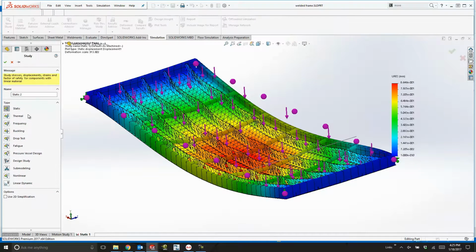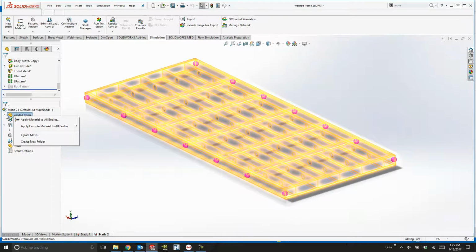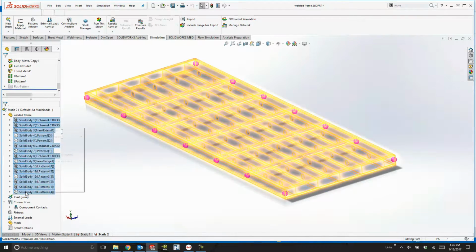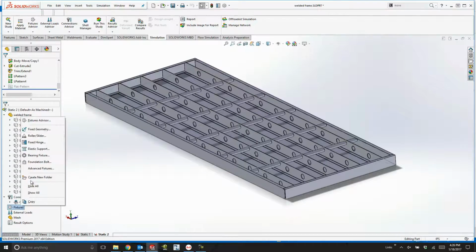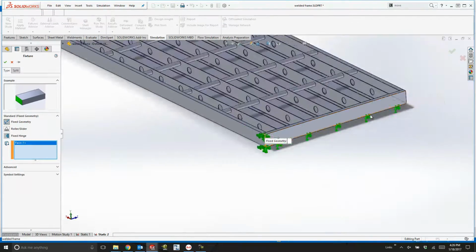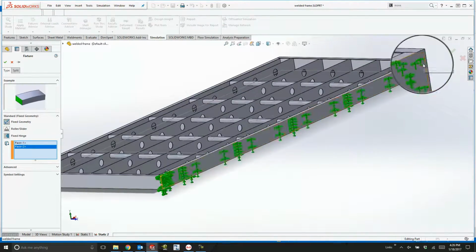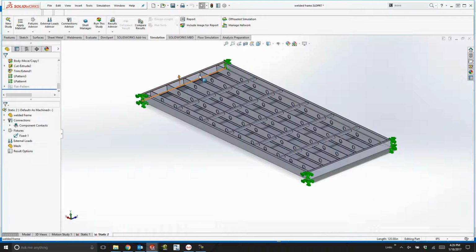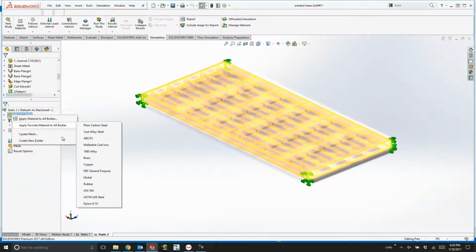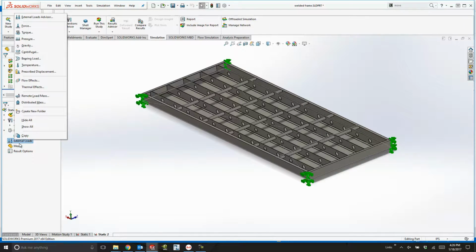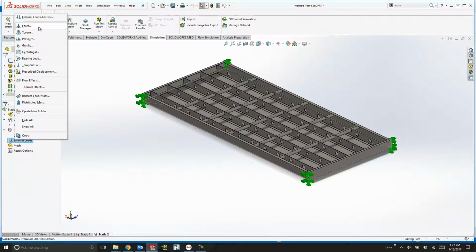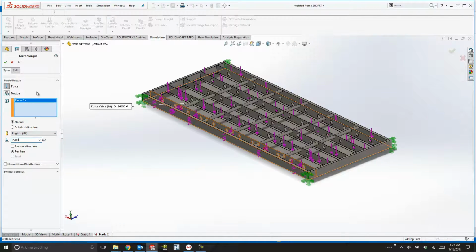However, what you may see is we're going to end up with different aspect ratios, and we're going to end up with some difficulties doing the mesh. You can override it, whether it was made with or without a structural member. You can still tell it to treat it as a beam or treat it as a shell or a solid, and kind of override that material or that mesh type. Bring over the force and get it all set up.